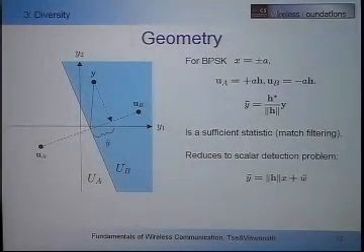So now, when are we going to be in deep fade? So now we have a channel derived from our coded and interleaved system, repetition coded, simple. Okay? When are we going to be in deep fade? When are we going to be in trouble? Sorry? When the norm of h is less than 1 over SNR. When the norm of h squared is less than 1 over SNR. That will be the deep fade event.